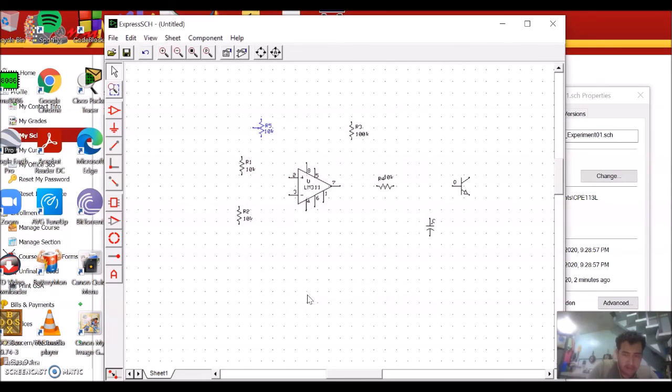Now we're going to add some components, the photoresistor that we need and the buzzer that don't exist in the library. Let's start with the photoresistor. The easiest way to make new parts is to start with a symbol that's already close to what you want and modify it. Place a regular resistor on the layout using the placement tool passive resistor. Let's go to the selection tool, the arrow, and then go to the component menu at the top and select ungroup component.